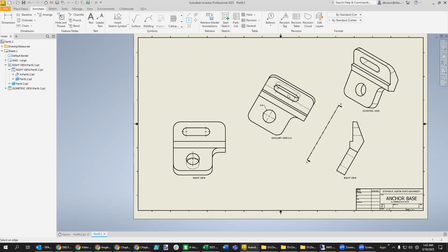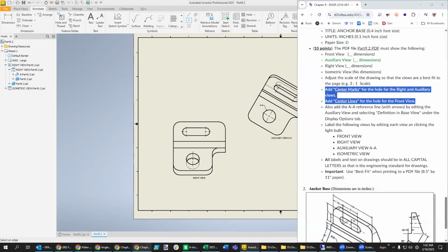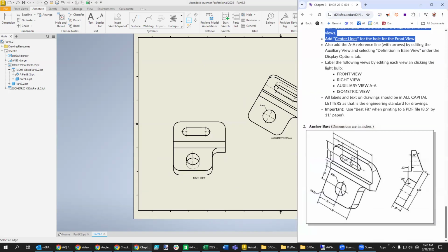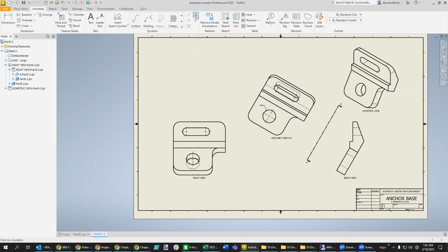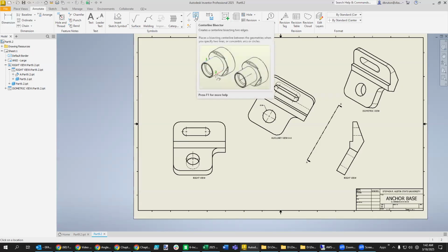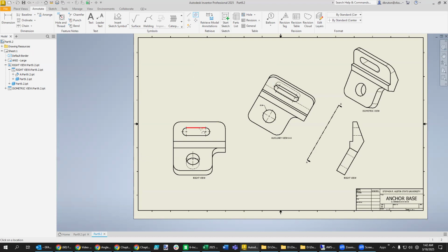And then in order to connect the lines that go across there, as we probably see down here, you see that line that goes all the way across? We need to use this other option up here to the right. If we hover over that one, we see that it says center line bisector. And basically it means select the two lines right here, and then I'll connect it with a bisector. And so, you don't always need those. It looks like it's maybe mostly when you have a slot, that's when you want to use it.